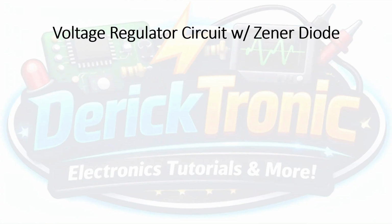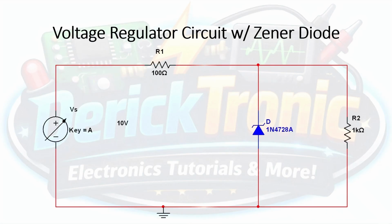Now, let's take a look at the voltage regulator circuit we will be constructing in this video. That circuit would look like this. For our power source, we will be needing a variable DC supply, as you see here on the left. Connected on the positive side of that power supply is a resistor here. That resistor I would like to call a limiting resistor. The job of this resistor is to limit the current flowing through this branch. Now, at the end, we have a load resistor there,